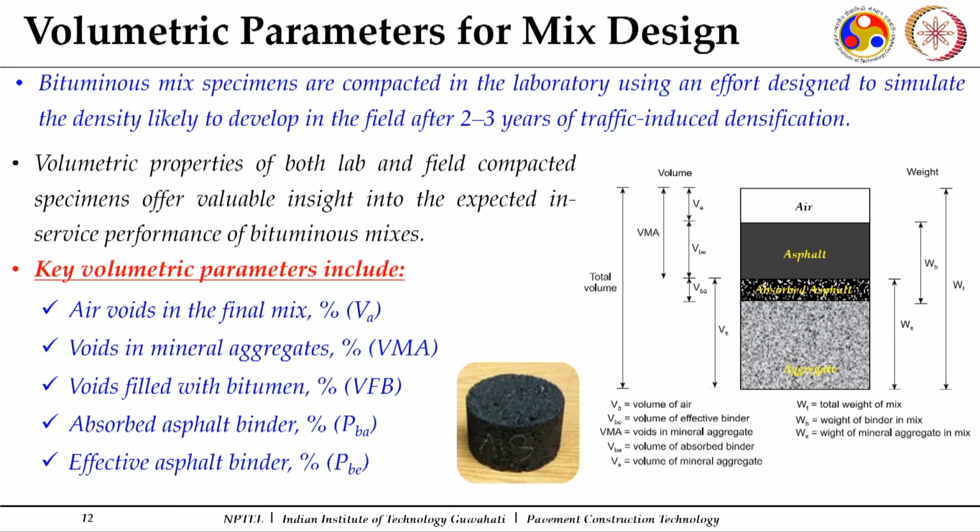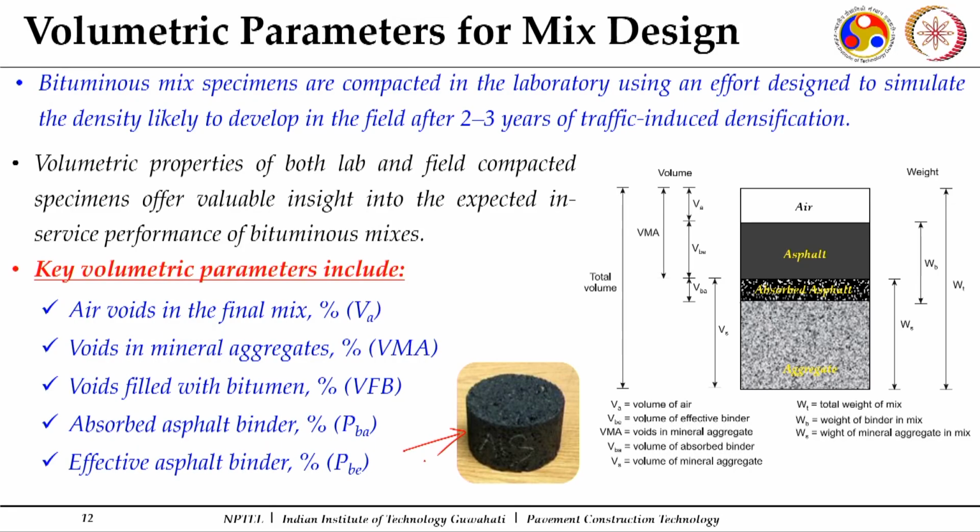When it is compacted, you apply a compactive effort, and that compactive effort should be the one which can give you a density which will be there after 2 to 3 years of service life. So, this is what you can see: this combination of aggregate and binder, when compactive effort was given, these cylindrical specimens got prepared.